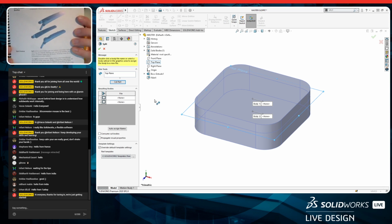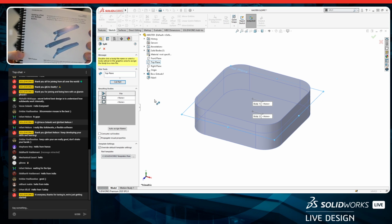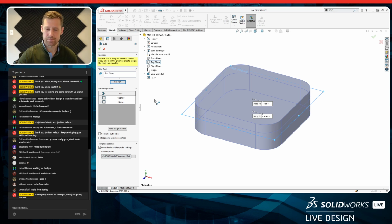I have an example here of where that might be very helpful. This is just a handle and it's split into two parts, and then after you split it, you add the manufacturing information in there. So as far as master modeling tools, I don't necessarily recommend this one. It has very little options here, so we're not going to choose it, but it is very useful for splitting the part into pieces if I need it.